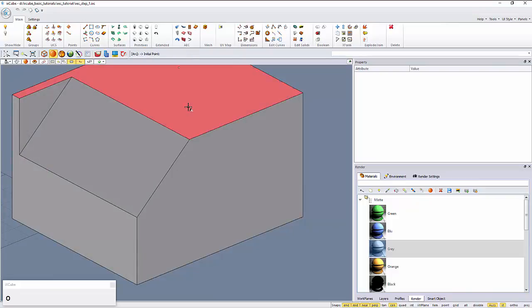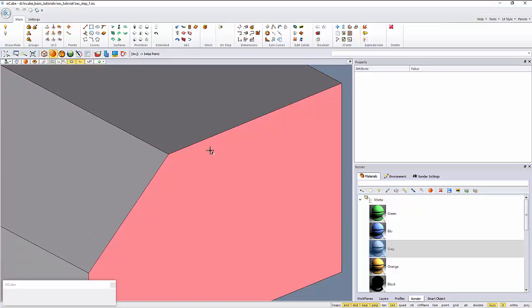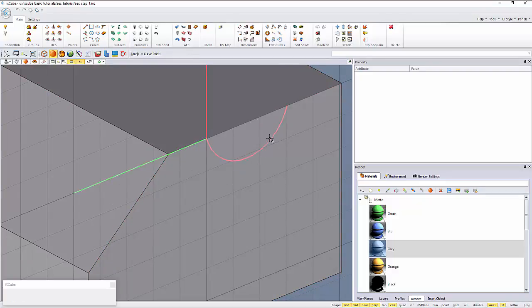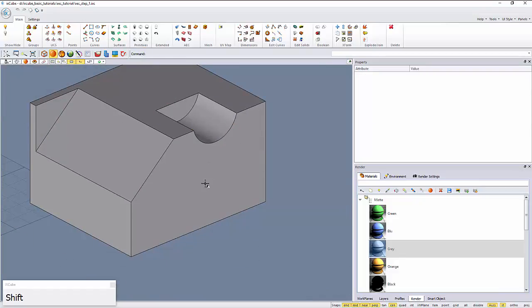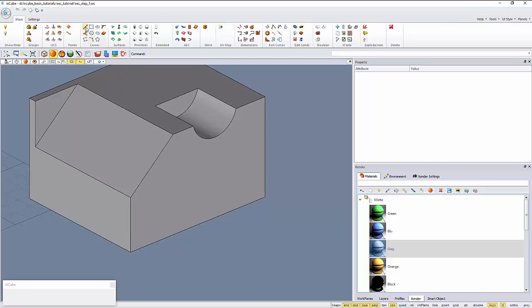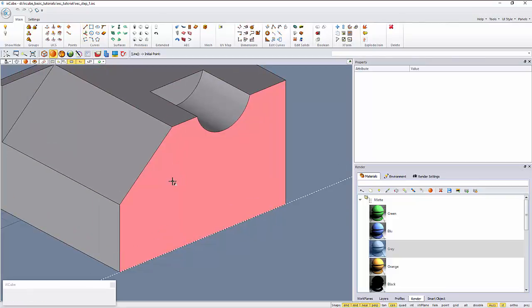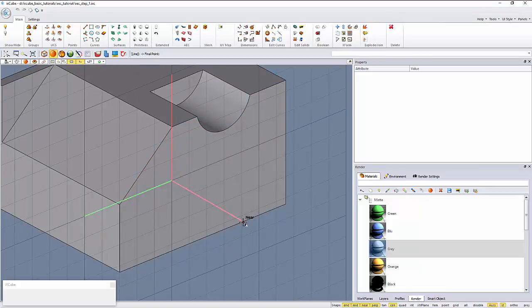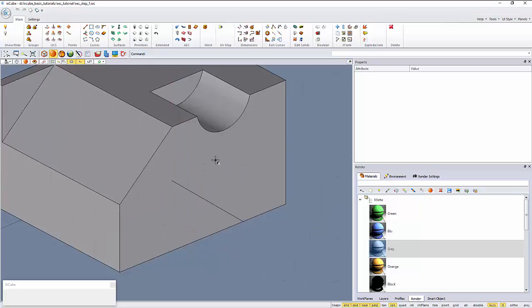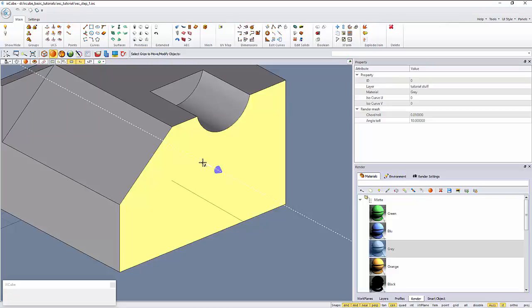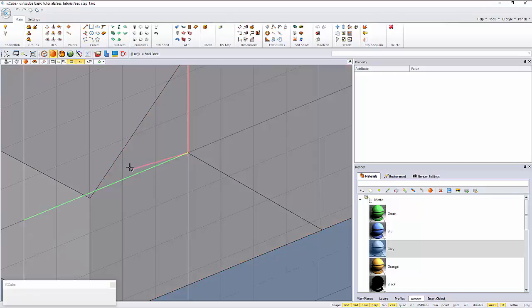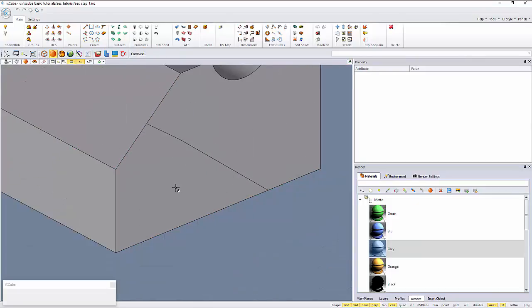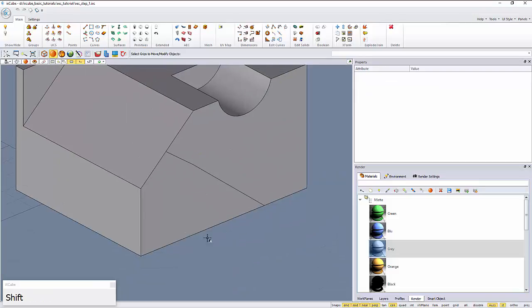Let's draw another curve. Start, end, and on an arch. I'll start drawing again on this surface, here, here, and down like that, and we can pull off part of the surface. Be aware that if you start drawing on a surface like this, but the surface is not split by the curve, it will be clear because you don't see two parts. But we can continue making another curve, for example, from here on the edge, and now we have our surface split in two pieces like this.